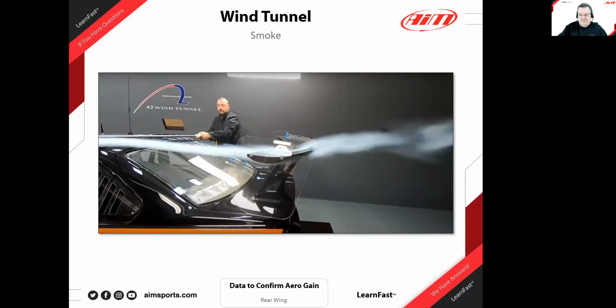And it's very, very interesting to watch that smoke in this area. Yeah, that wing is not one of ours, but it was still pretty neat to see. You can kind of see a vortex starting, how the smoke trails off a little bit, and the customer who owned the car cut those end plates out of a sheet of Lexan or plexiglass or something, which actually made it kind of neat being able to see the smoke. Exactly. The smoke tells you some things that the wool tufts do not. But yeah, larger end plates, another rule of thumb situation, generally bigger is better up to an extent.